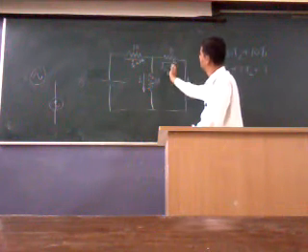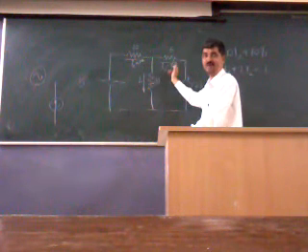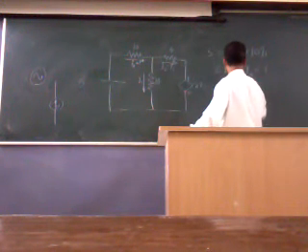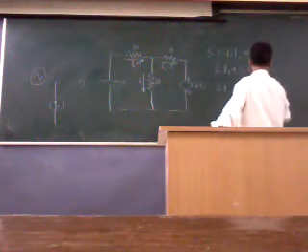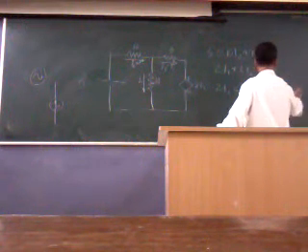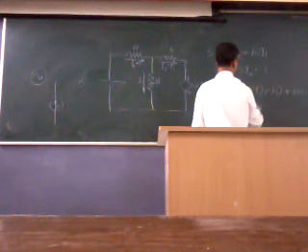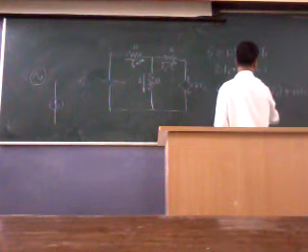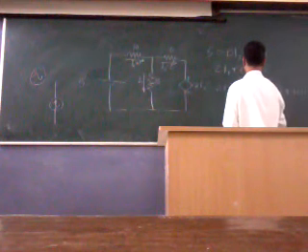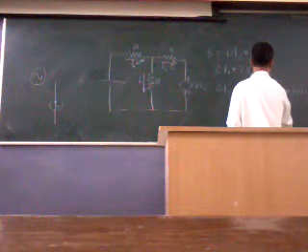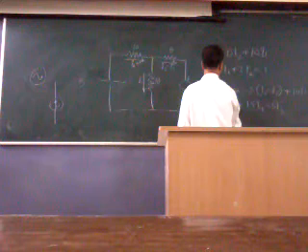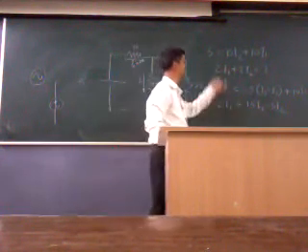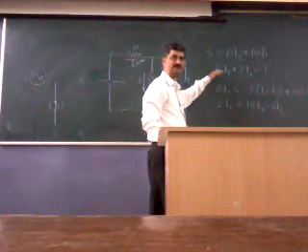Then for the second, 2 I1 is equal to, it is reverse. So 5 into minus (I2 minus I1), or 5 into (I1 minus I2), correct? Minus 5 into (I2 minus I1) plus 10 I1. So what is that? 15 I1 minus 5 I2 is equal to 2 I1. So put this 2 I1 here, by substitution here.